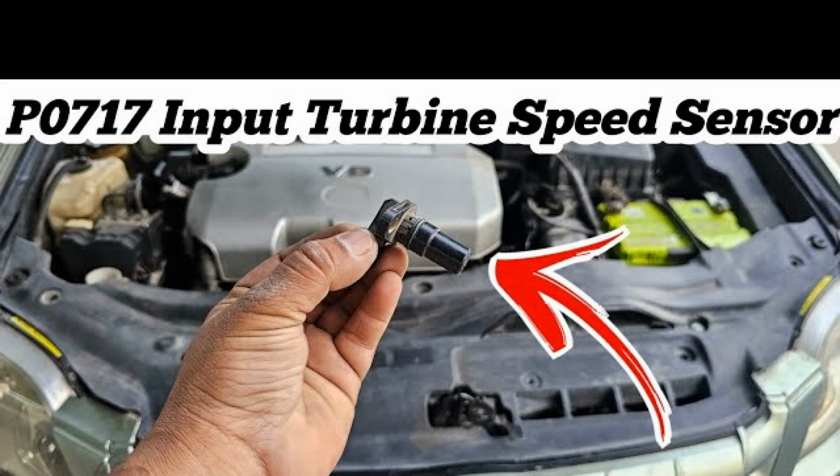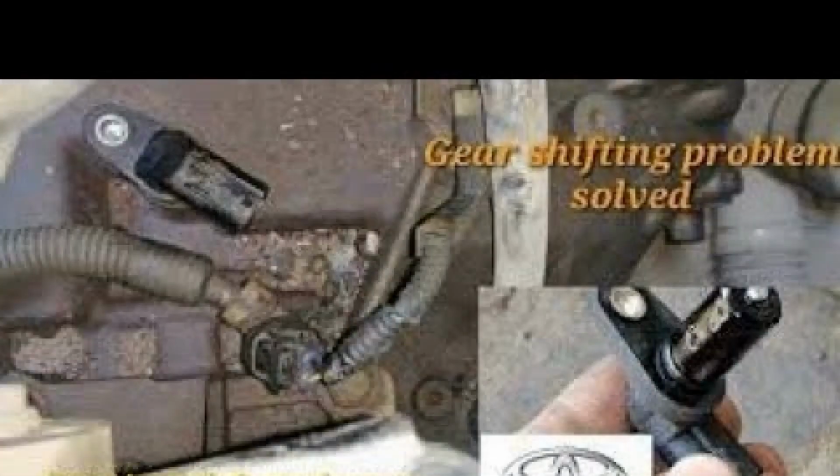What does the P0717 code mean? Diagnostic Trouble Code, DTC, P0717 stands for Input Speed Sensor, Turbine Circuit, No Signal. This indicates that one of your car's computers perceives a problem with the speed sensor or its circuitry. The input speed sensor, sometimes called the turbine speed sensor, tracks the transmission input speed. The powertrain control module, PCM, or transmission control module, TCM, identifies the transmission input speed in revolutions per minute, RPM.